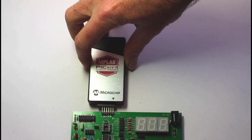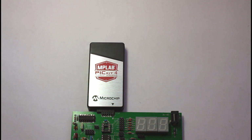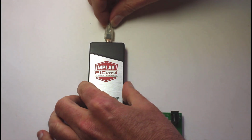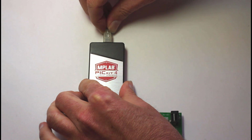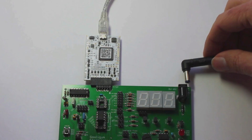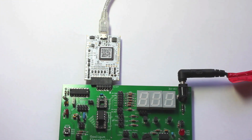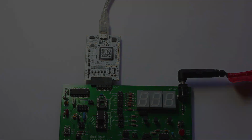If you have a PICkit 3 or PICkit 4 programmer, plug it into the training board with the arrows aligned, and connect it to a USB port on your computer. The PICkit can supply power to the board, so that's all the hardware you need for this lesson. If you have a Snap programmer, you'll also need to supply 5V to the training board's DC jack. Now we're ready to write our first PIC program.